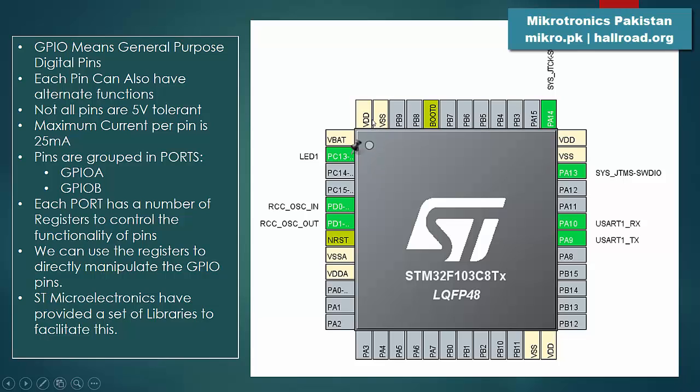because the digital circuitry tends to have noise when it switches on and off, and analog systems usually require a very clean power supply, which is free of this noise. So most of the times when you make your own circuits, which are more sensitive sort of circuits, and they need a clean power supply to the analog circuitry, you provide a specially filtered power supply to these things. But in most of the cases, you can just tie these together. This VDDA and VDD can be tied together. This VSSA and VSS can be tied together, and you can give the same power supply.